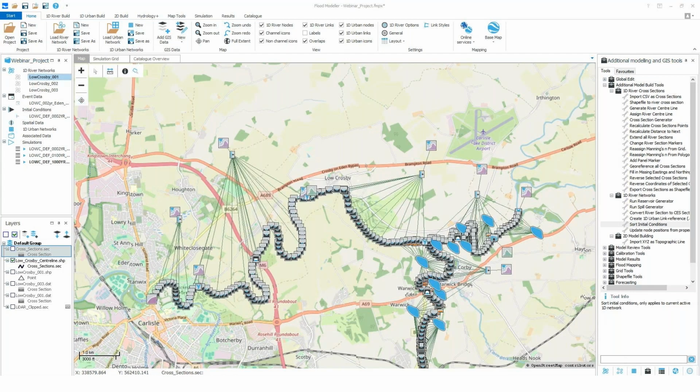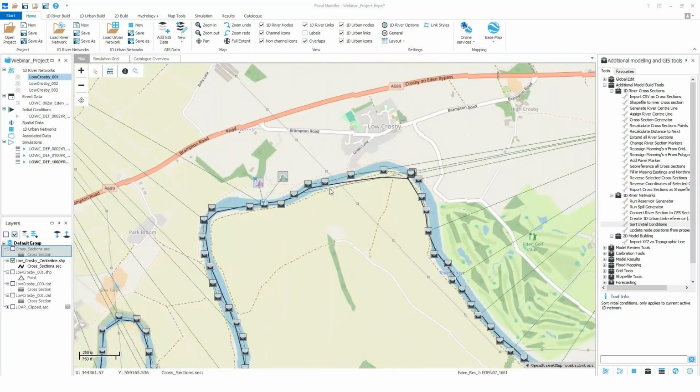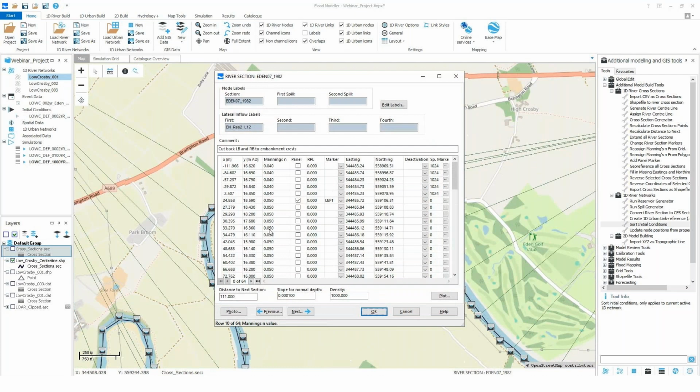Global edit tools are really helpful for making changes to your model in a few steps rather than taking the time to go through your units one by one. An example I can draw on here is updating the floodplain roughness using the roughness tool. If during a model review you find that your floodplain roughness is set to 0.05 Mannings, and on inspection you actually think it should be 0.04, the global edit tool can be used to update all the values within your cross-section at once.